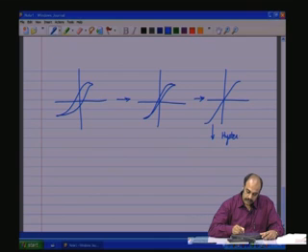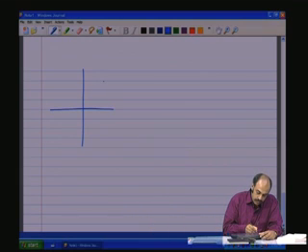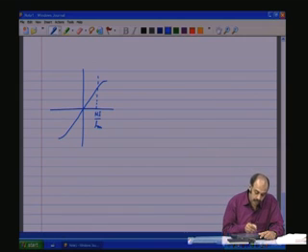Here hysteresis loss is equal to 0. And then we also need to look at the slope of this. This slope tells you how much magnetomotive force, Ni1 by Lm, that is, how much current I have to pass in the primary of the coil to obtain a flux phi 1 by A for a given core.